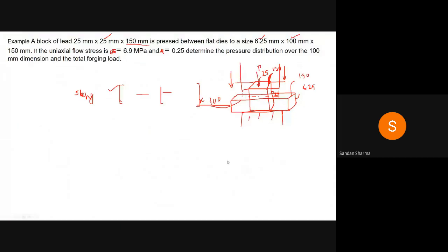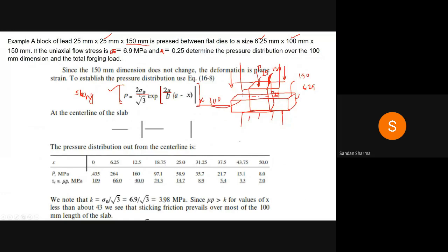Yes. So if you consider this point, first we are considering the pressure required, the pressure distribution at each x point. If you put x equal to 0, no movement, you will have the maximum condition. At x equal to a, you will have the minimum condition. X equal to a means this complete part will become 0, and e to the power 0 means 1. So you will always have some pressure required, for the sliding condition at the free surface.